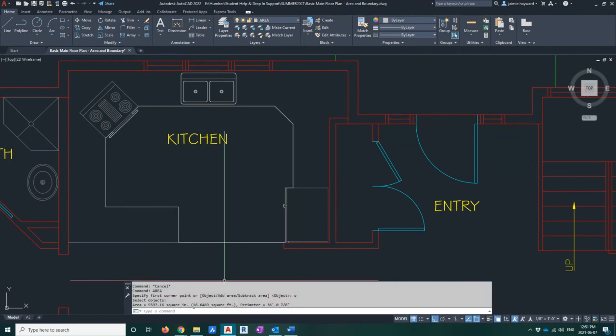Go into my polyline, and just like that, it tells me 66.6 square feet. Well, I would round that up to 75. I would tell my clients, or sorry, my trades, I need 75 square foot of tile. Because again, cuts, off cuts, spare cuts, mistakes. And then that way that counts for going straight here with my tile. All right, and that's how I round it up.